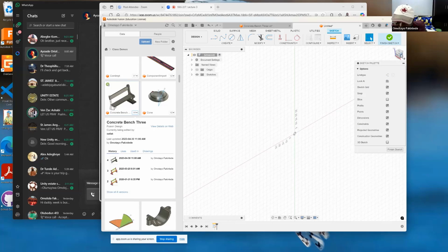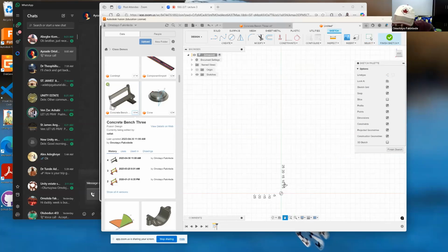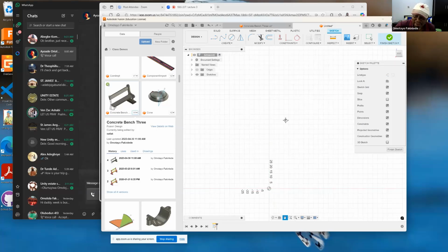So I want to pan. To pan, I will take the pan item inside the navigation tool set, and I will move this thing down. So I panned it. Having panned it, what do I want to do next? When I'm done with the panning, I use escape to go back. I want to create 3 circles at the origin, with radii 50, 60, and 73.